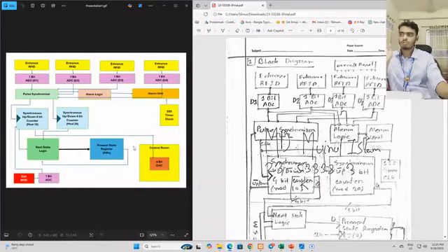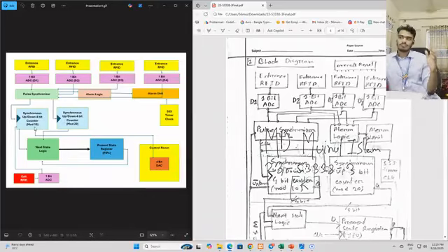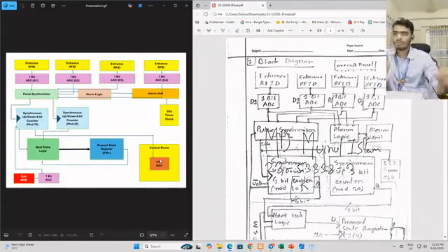And lastly we have a control room where a 4-bit DAC is placed. According to our requirements, in the control room, they need to see the passenger count at the platform. So this counter is connected with this 4-bit DAC, and they can apparently see only the analog signal. As this is a 4-bit counter, it sends a 4-bit signal, and this comes into the DAC, digital to analog converter, and it converts into an analog signal which can be read by the control room. So there goes our block diagram.